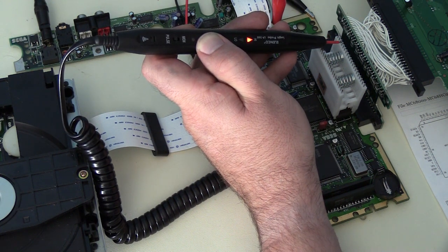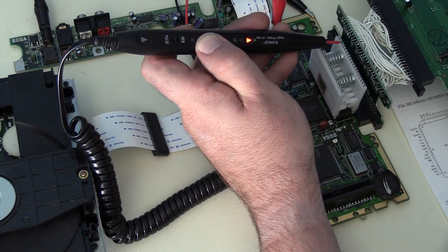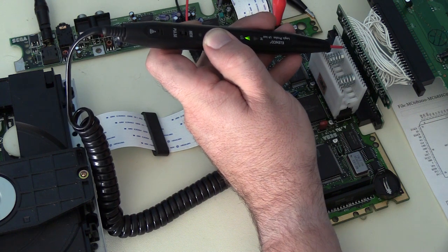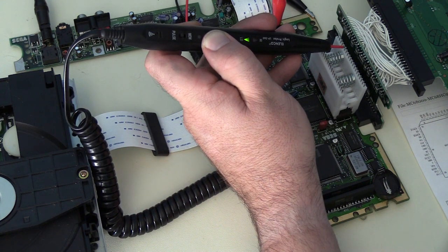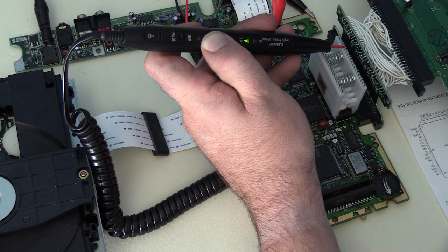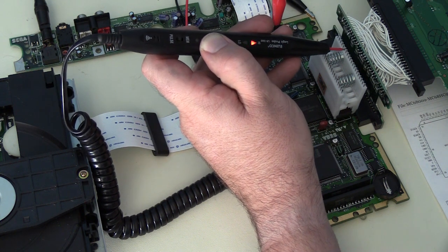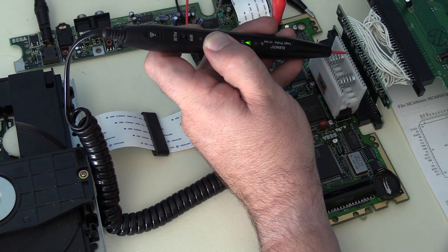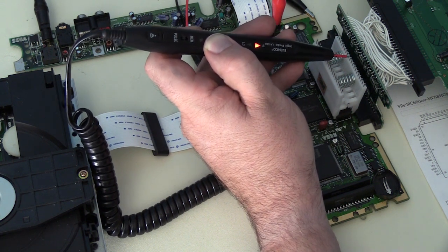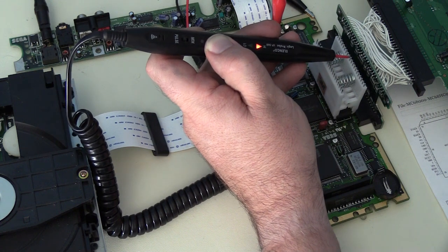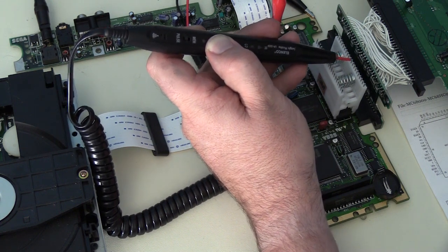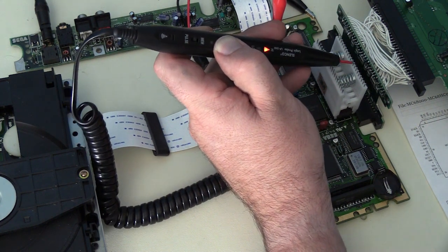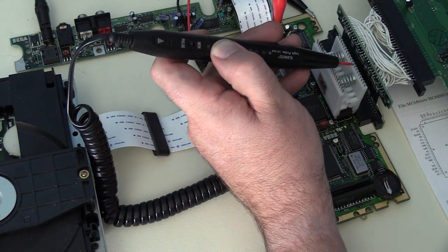And it looks like our data lines are all being held low, all our address lines are being held high. Well, maybe not. That one's, let's see, that's A13, it's going low. So some of the address lines are going high, some of them are going low, but the point is there's no activity, and there's no activity because the system's crashed. That's why I had to go to the logic analyzer, because I wasn't learning anything from this, since it wasn't showing any activity.